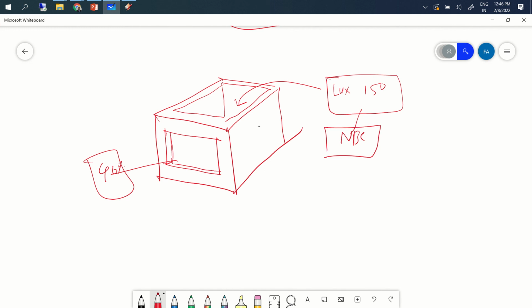So for example, when you discuss your design, often we will say that this corridor is not lit, we need light here. When we say we need light here, how much light do we need? For that, we should go back and check the standards, right? NBC says we need a minimum of 150 lux for corridors and public spaces. And for different activities, different numbers are given.